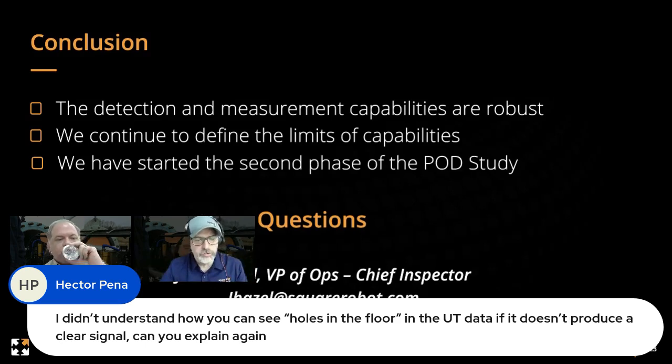If there was a hole created by corrosion, we would see the walking of the corrosion and be able to get measurements of that. And then, just as John said, there would be an absence of sound. There would be no return because there's nothing for the sound to kick back up on us for. So we would look for that emptiness. In our system, it would be blue. You saw the B scans earlier. There would be no lines going across anymore. So that would be our first indicator.